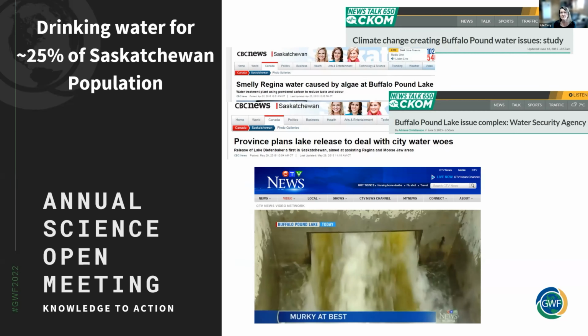Now, some of you may have seen this slide before, but these articles are from May 2015. What happened was you had poor water quality entering Buffalo Pound during spring freshet, combined with unusually mild, calm spring weather. That led to an unusual spring stratification event of up to an 8 degree gradient. That was very unusual for this time of year. It led to complications in the water treatment because the warm water was entering the clarifiers, rising to the top, carrying the floc to the top before it could settle out. This led to a delay in treating the water, which subsequently led to water restrictions in the cities of Moose Jaw and the provincial capital, Regina.